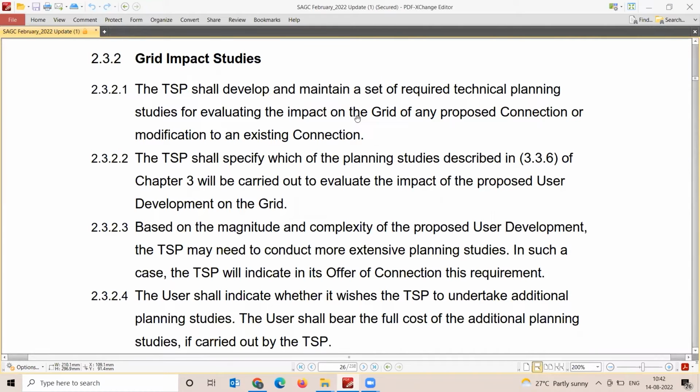If the power factor of a 50 kVA consumer is too low, then that will create a voltage drop in the distribution system, which is not acceptable for a distribution utility. I guess, Anurag, that's clear.